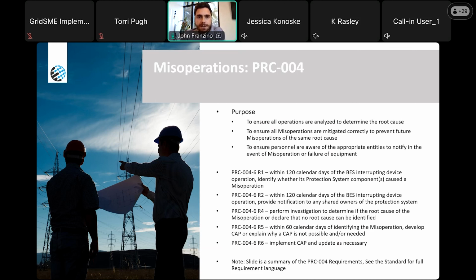Because protection systems are there to protect the generator or the elements of the system, but we don't want them to trip too early, right? Which maybe results in a grid reliability issue where we're actually exacerbating the disturbance on the system rather than supporting, or vice versa, not tripping at all and then risking plant damage and safety issues.